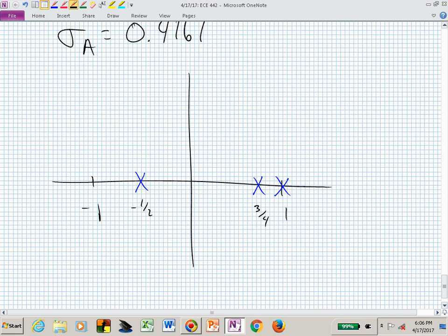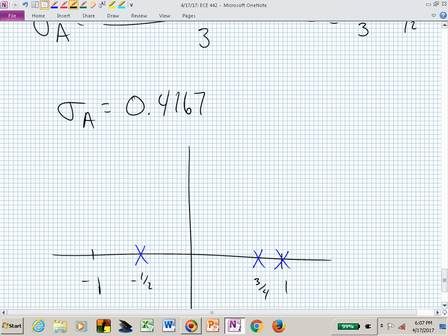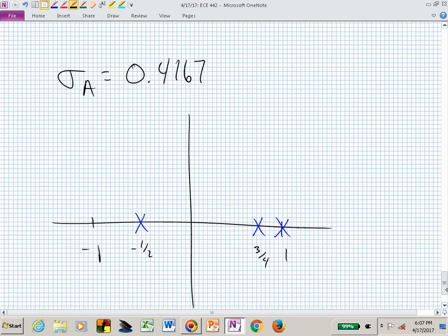Where are these guidelines? Where are the asymptotes? Sigma sub A is at 0.416. So if you're accurately sketching this, you're 41% of the distance between the origin and 1. Meaning you can now say, if this is half, let's say that this is now 0.416. And from that point, I have an asymptote at 60 degrees, 180, which is the negative real line, and 300. Or I can now sketch this.